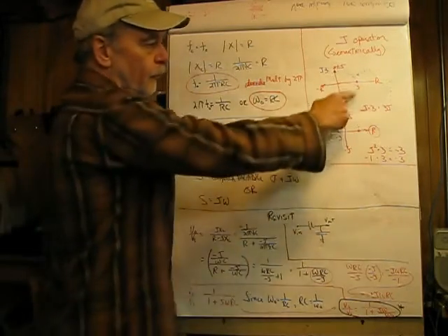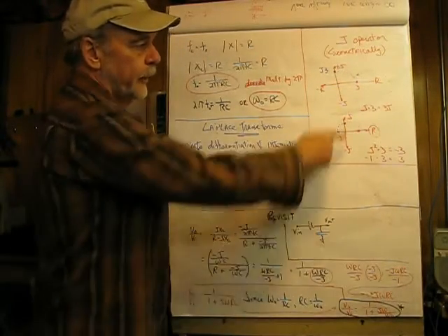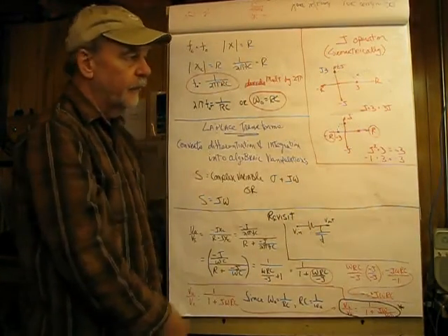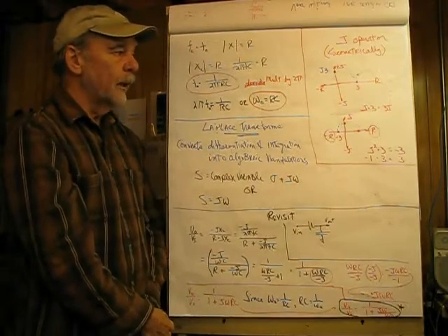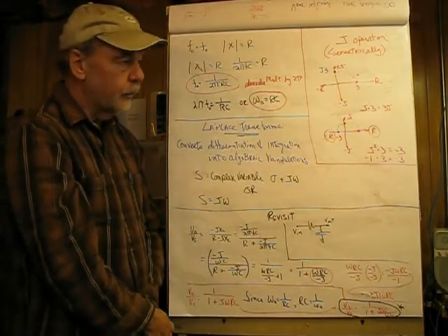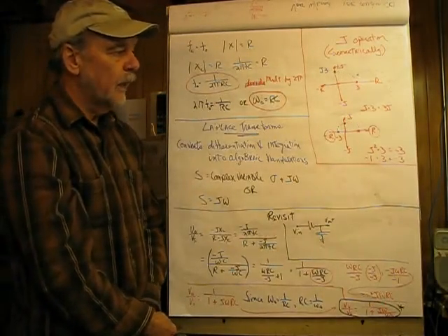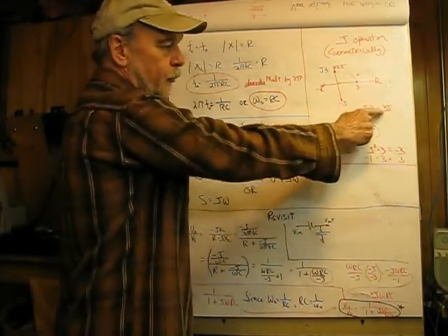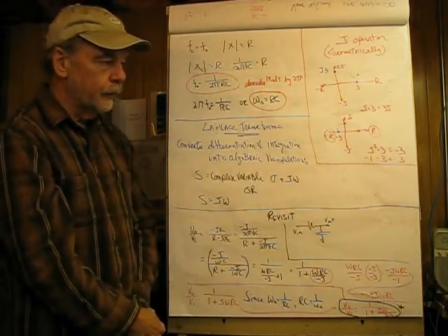So we're going to start out here with a value of 3, and that can be 3 ohms, we'll say. And if we multiply it by J, all we're going to do is rotate that 90 degrees, and then we're going to specify that value as J3. So what we can say here is when we multiply J's together, we're going to be moving counterclockwise 90 degrees, and if we were to divide them, we'd be moving clockwise 90 degrees. So we would express this then as 3 times J, or 3J. So 90 degree rotation per J isn't bad.